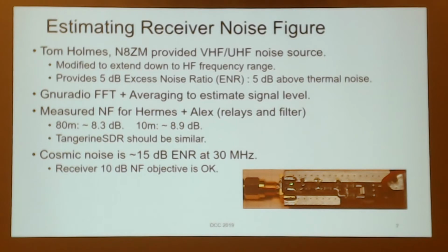And so I basically tacked a 0.1 microfarad capacitor across the existing 10,000 pF coupling cap and moved its bottom end down into about a megahertz or so. Well, it's not too bad, actually. At least in SPICE modeling, it doesn't affect it too much. I'm sure it affects it badly at UHF, but down at HF, it's pretty insensitive to that.